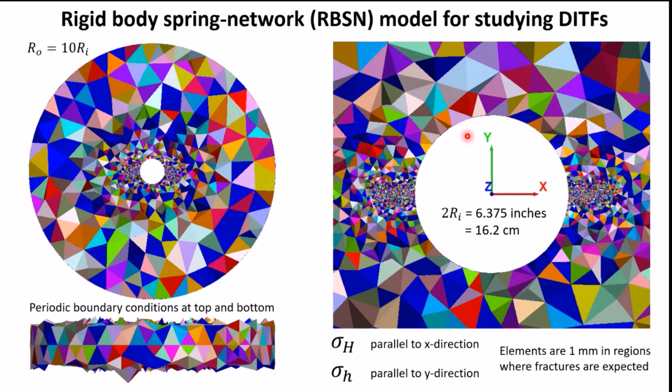So usually the stress criterion is not very good for cracks, because at the crack tip, the stress field is very asymptotic. So some people think the energy-based criterion is better for crack propagation. So they have different criteria for crack propagation. Based on my understanding, that's a bit complex.